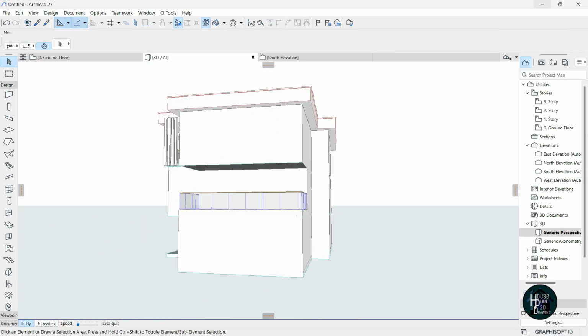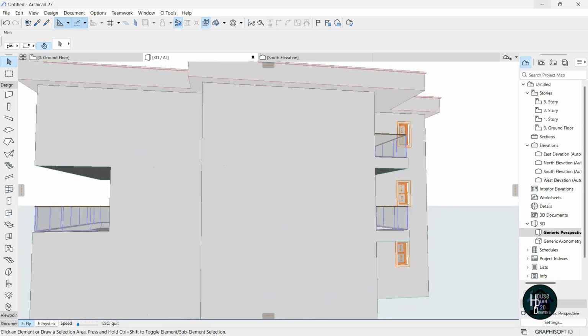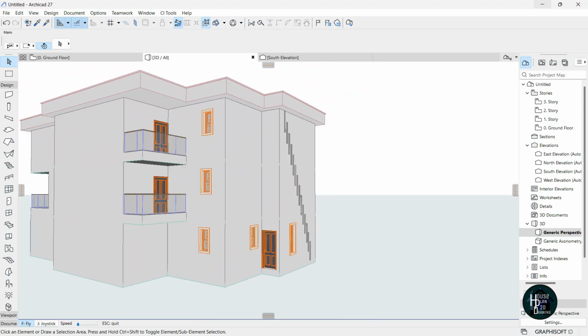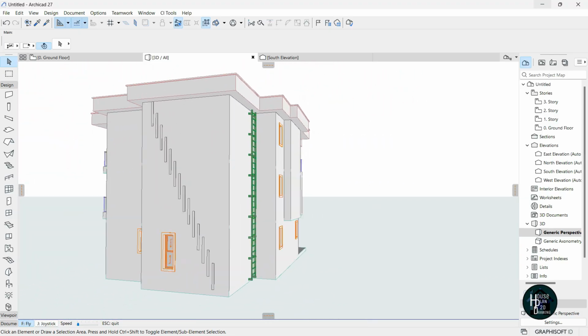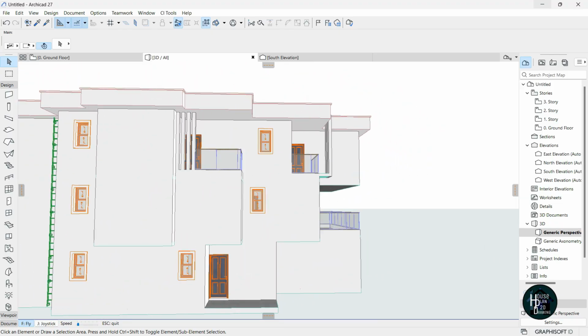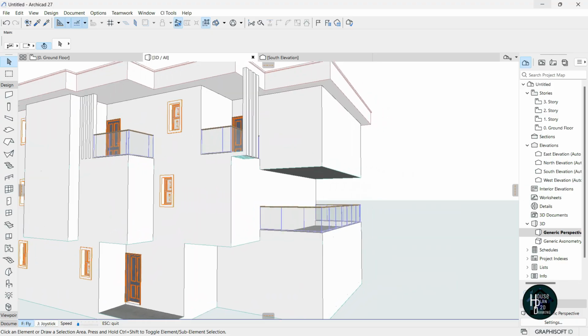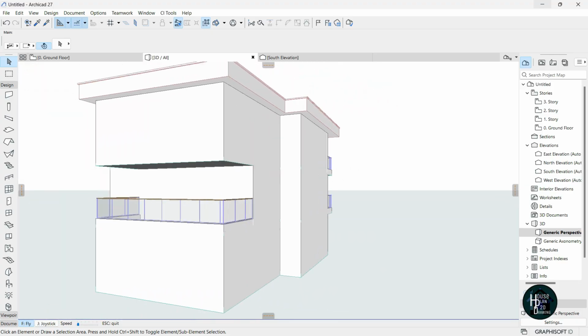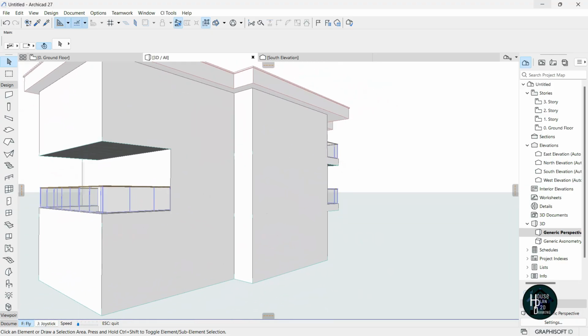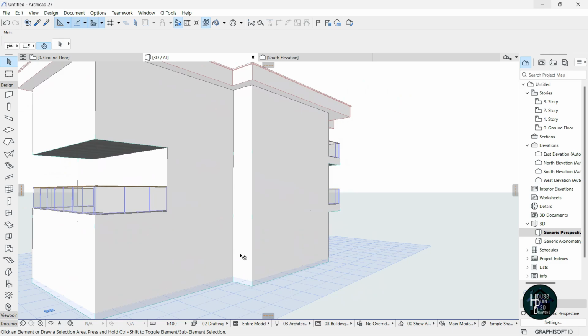As you can see, we've come to the end of the external side. We've made the features for the external side. What needs to be done now is to use the curtain wall to fix the proper windows for this particular design. Okay, and if you come to this side, I want us to fix the stair walls for this side first.